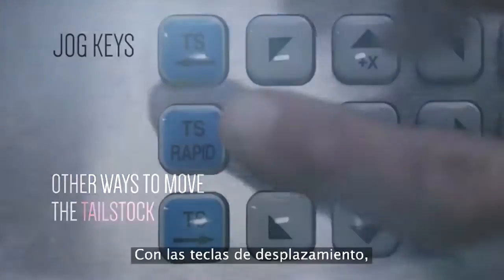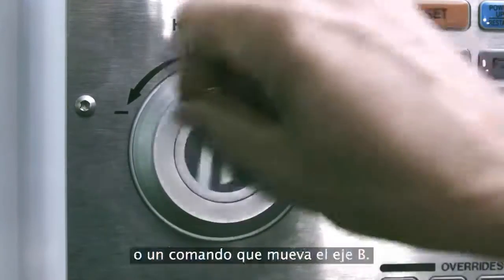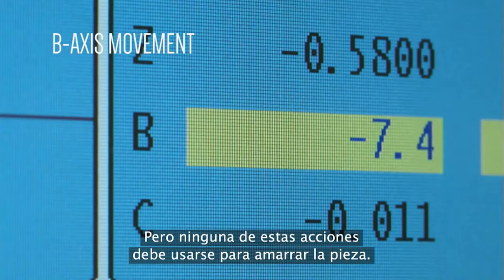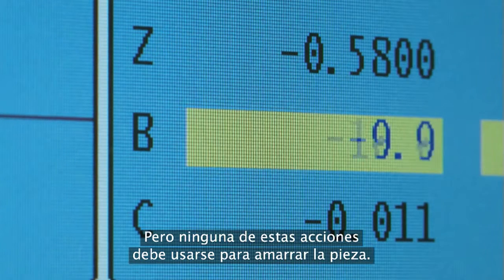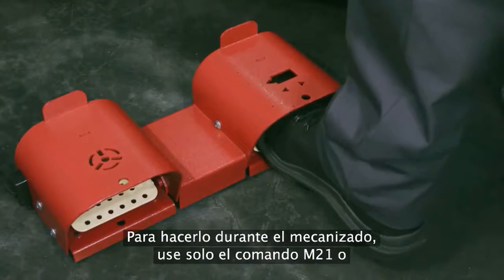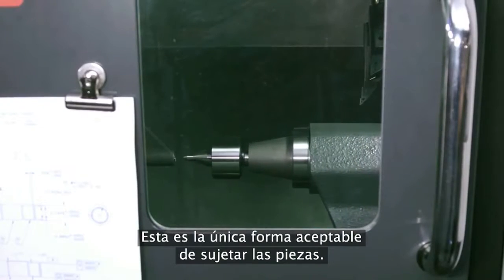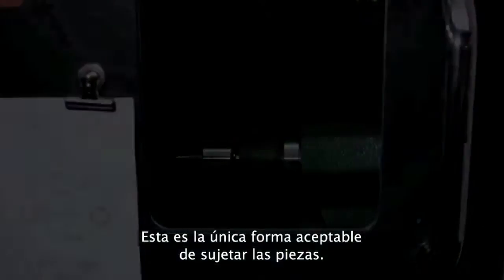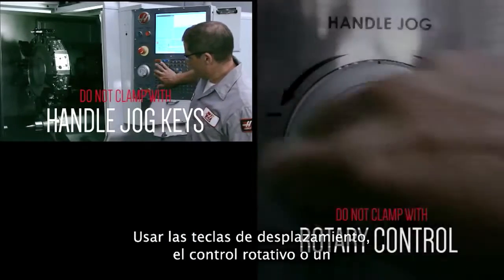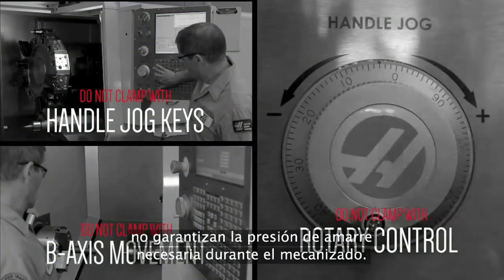And there are several other ways to move the tailstock. You can use the tailstock jog keys, handle jog the B-axis, or command a B-axis move. But none of these should ever be used to clamp the part. To clamp your part during machining, use only the M21 command, or the foot pedal, to initiate the M21 move. This is the only acceptable way to clamp your part. Using the handle jog keys, the rotary control, or commanding a B-axis move will not maintain full clamping pressure during cutting.